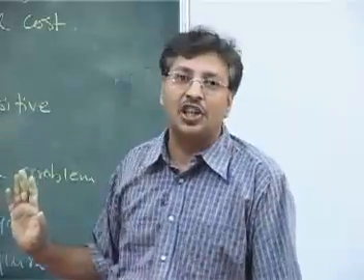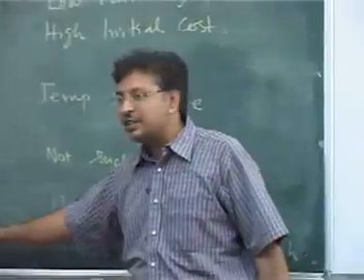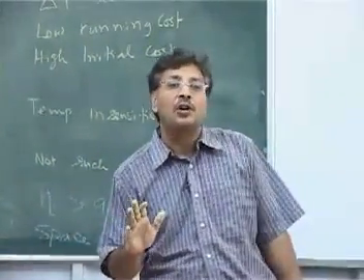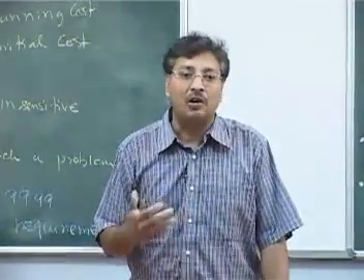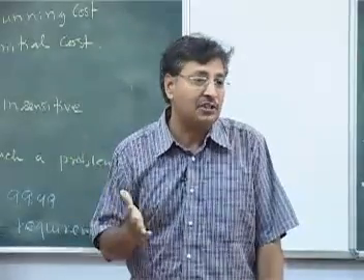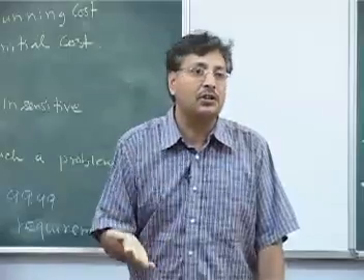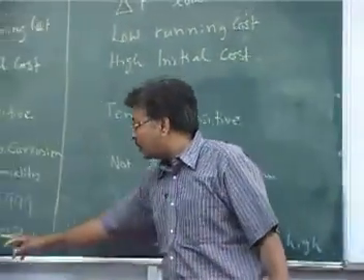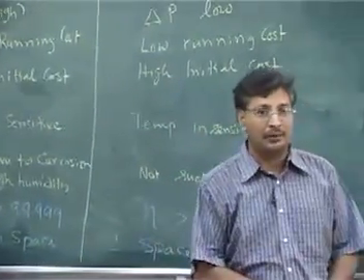But trends are changing, because of two things. Efficiency is higher, and some very old power plants in India do not have enough space to put ESPs. The laws are changing, and the government would say: we don't care whether you have space or not, control the emissions or close down your plant. Closing down the plant is not an option. So even power plants now, because of the low space requirement, go for bag filters.